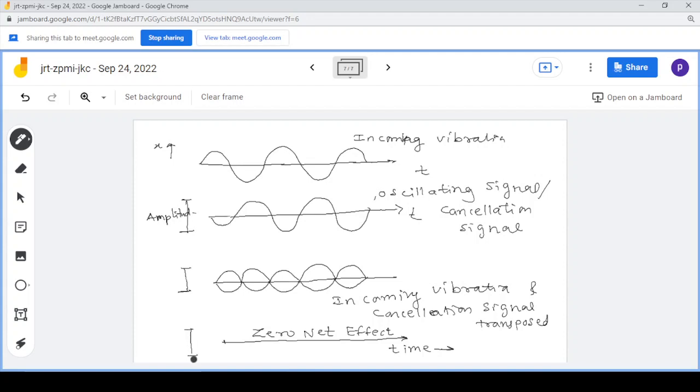Okay, if this is the vibration we are measuring, there will not be any vibration subjected to the system, because the actuator is giving the vibration to the system in the opposite direction, whereas the system is getting vibrated in, suppose, the downward direction. The actuator is going to give the amplitude of the motion in the opposite direction to the vibration, and we will get this pattern. So this is how the active vibration system works.